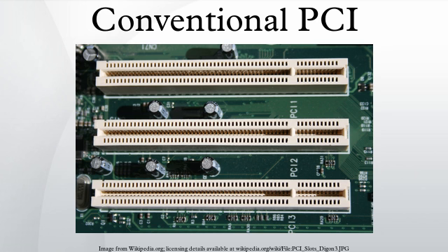The direction of the data phases may be from initiator to target or vice versa, but all of the data phases must be in the same direction. Either party may pause or halt the data phases at any point. Any PCI device may initiate a transaction.